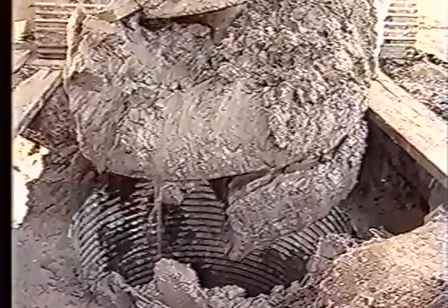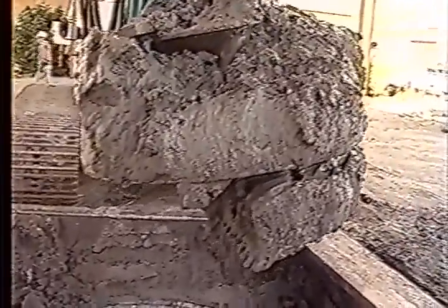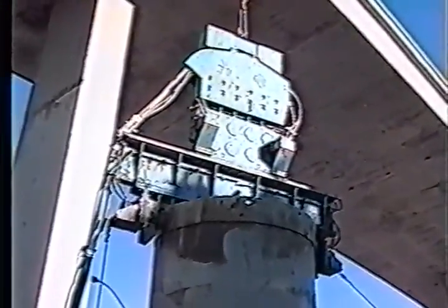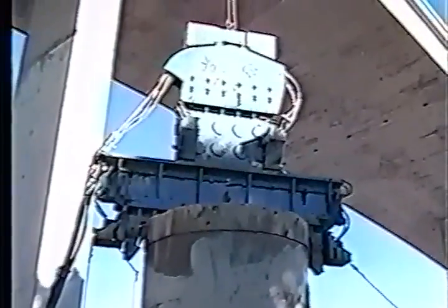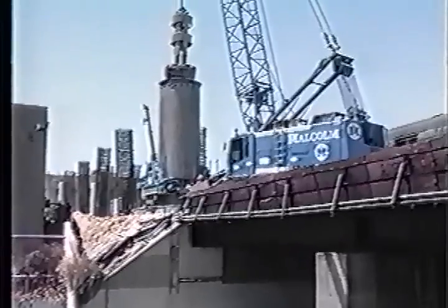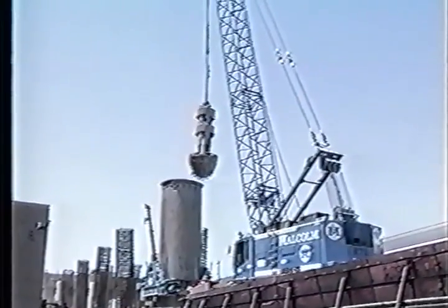The slurry method can consist of circulated water suspensions, or mineral and polymer slurries may be added. A casing can be placed in the hole by an impact or vibratory hammer to support the excavation. If necessary, the steel casings are joined by welding and separated when the temporary casing is removed after concreting of the shaft.